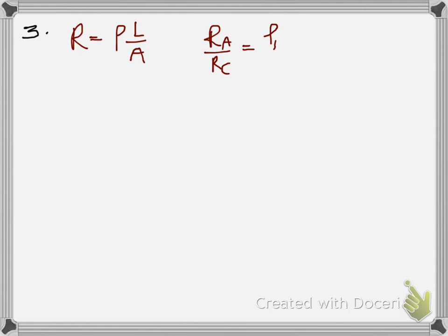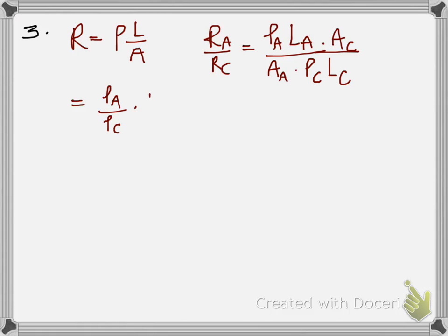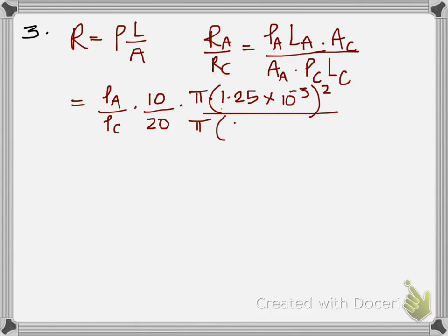Resistance is rho L divided by A. Rho is the specific resistance or resistivity. And I'm giving A as aluminum and C as copper. Okay. Subscript. So RA by RC will turn out to be that. Because when you divide, you flip the second one and multiply. That's what I've done. Okay. And therefore, RA by RC, because I was too lazy to look at the resistivities, so I just kept it as it is. And then area of cross-section is pi r squared, isn't it? So that's why you have to remember to square the radius. Again, I left it as RA by RC times, cancel the pi, cancel that, right?